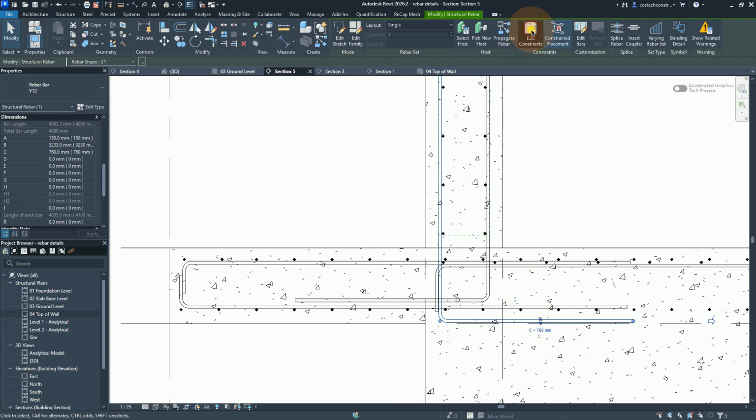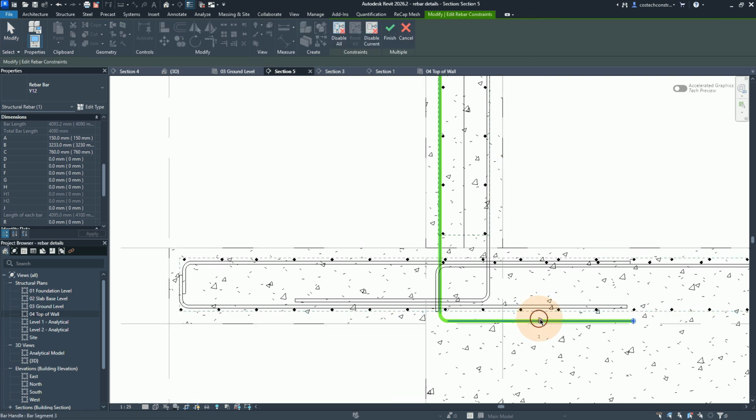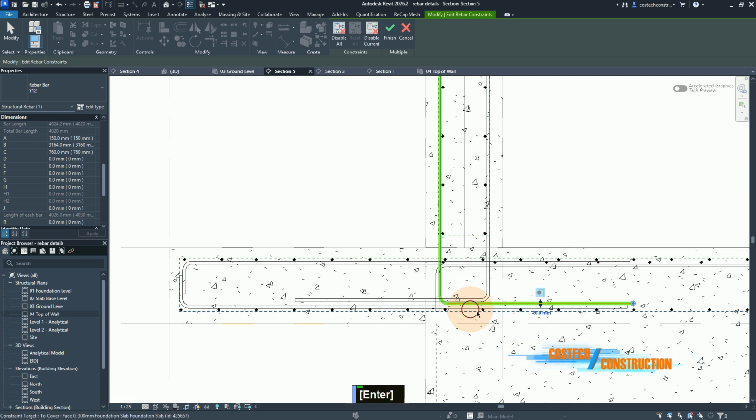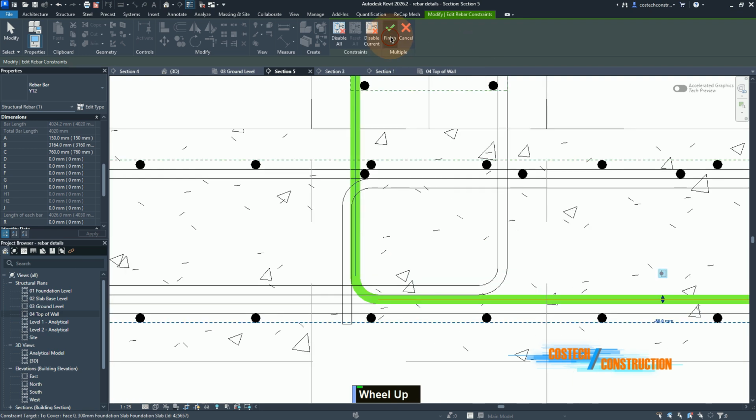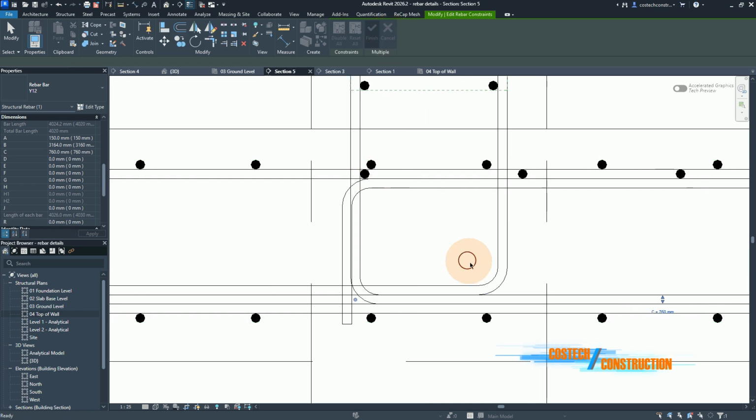You can go to edit constraints. I will select this handle. Then from here we can select this face, and now we can give it the -80 value for this side, so as to bring it here. Now if we hit finish, I will hit finish, and you see that this overlap also will be okay and it will not interfere.